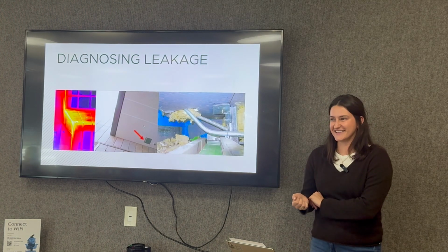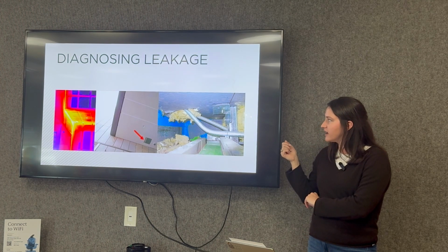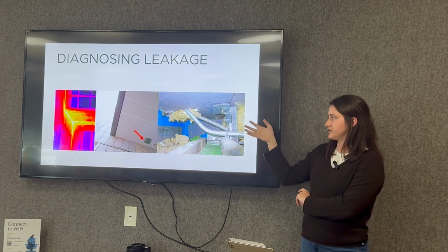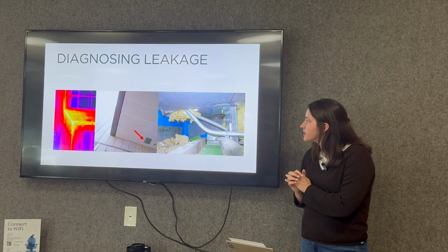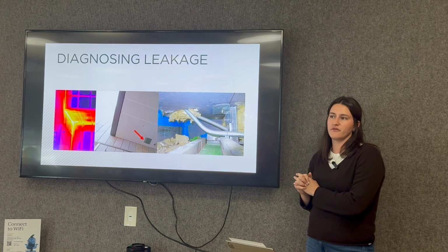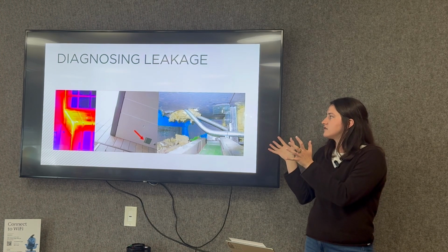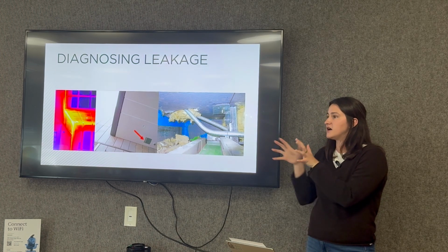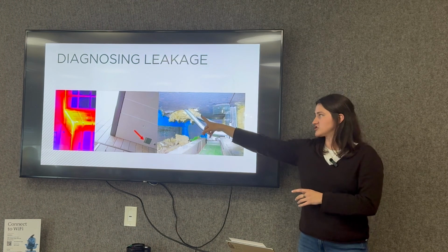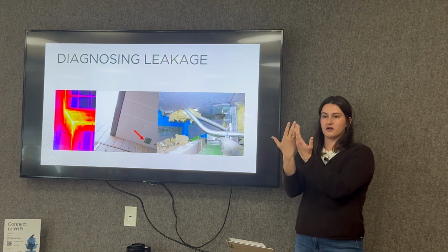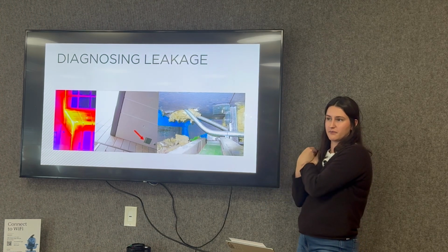Oh yeah. So someone had come to wire either the security camera or a light fixture, and they essentially just punched a hole through the exterior sheathing, which has the air barrier applied on it. Maybe that mineral wool was already there. Maybe they just packed it into the opening saying it was all well and fine, but somewhere where it's really cold, in this case, if this building was a museum, so if your building is positively pressurized, especially when it's cold, if it's really extreme, you get moisture collecting, and especially this mineral wool could hold a lot of water, and in that way, you might, in the winter, see icicles actually forming at the outside of the security cameras or the light fixtures.